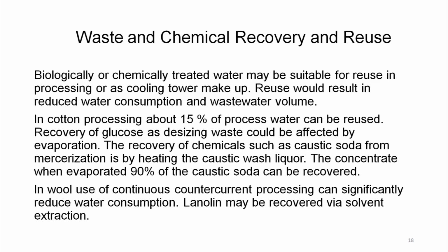In cotton processing, about 15% of the processed water can be reused. Recovery of glucose as desizing waste could be affected by evaporation. The recovery of chemicals such as caustic soda from mercerization is by heating the caustic soda liquor. The concentrate, when evaporated, 90% of caustic soda can be recovered.